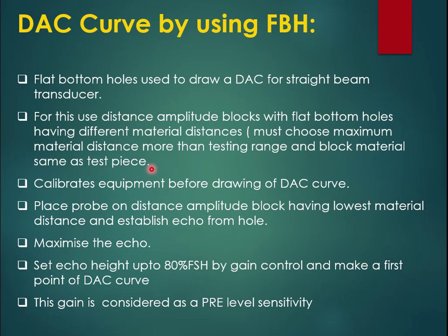So to draw the distance amplitude correction curve by using the flat bottom holes, take the different distance amplitude blocks, having flat bottom holes of different distances.